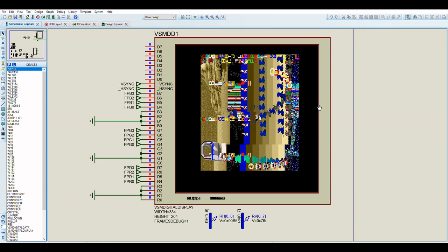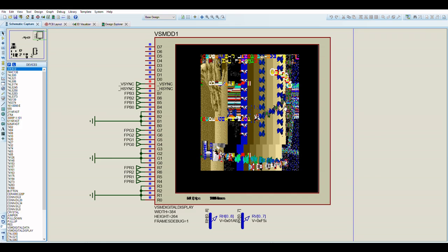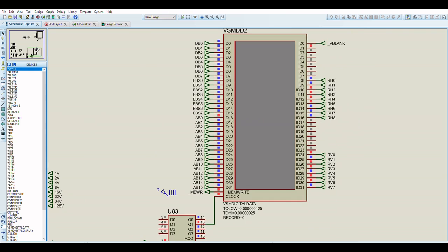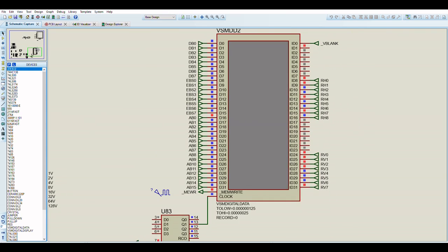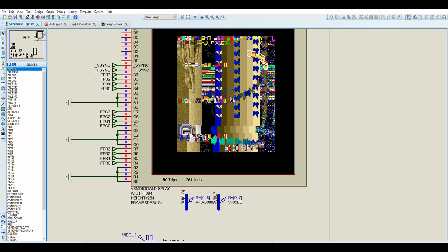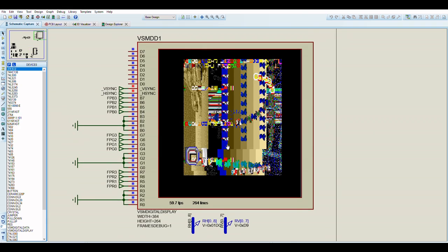So in this test data demo, I use, I think, C++ code to calculate all of these values for the sprite definitions and how they move. And I use the digital data generator to latch on the horizontal and vertical pixel positions. Also I use the v-blank latch to control when I can update all of these hardware registers.